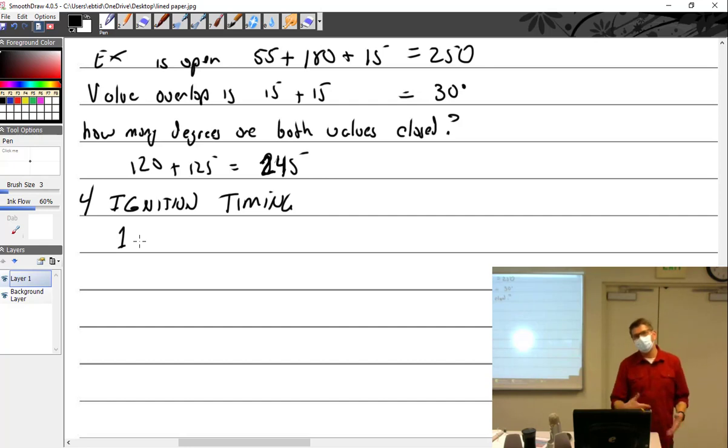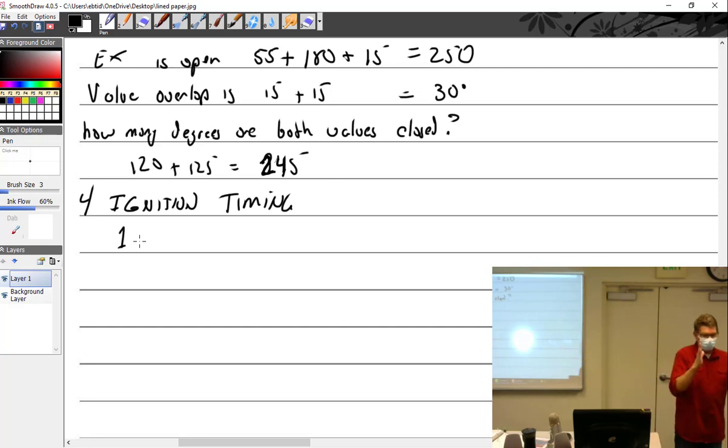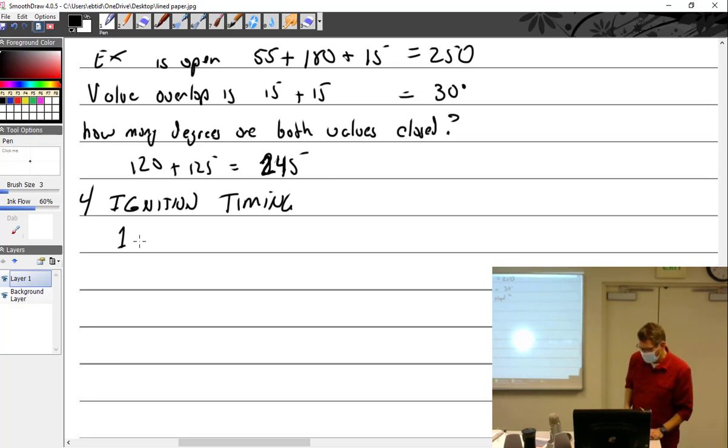And kind of the reason why Continental does it that way in the big engines is because these big old 6 cylinders, right? You can't add that much to the engine compartment. The engine is right up against the firewall to begin with, and there's no room to add a starter. So the engine's this way, and they want to add the starter this way, so it makes it a 90-degree angle drive. Whereas with Lycoming, they just put it on the bottom of the engine and go forward. And so that kind of works. Anyway, yeah, so you don't want this.